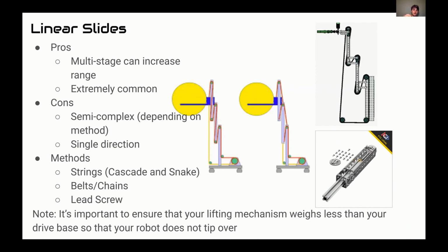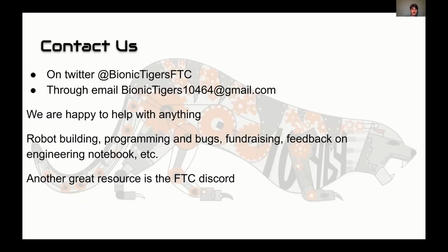So you just have to make sure that you have a heavy enough drive base that when you lift all this stuff up in the air and you start to go forward, your inertia doesn't carry you over and tip you over, which is a mistake that we've made very often.